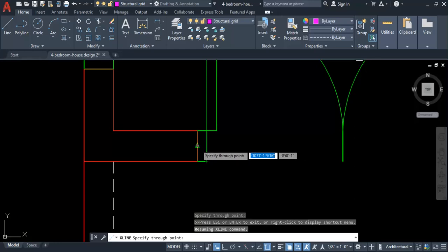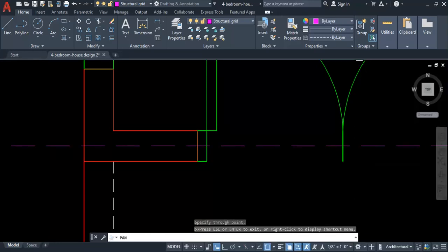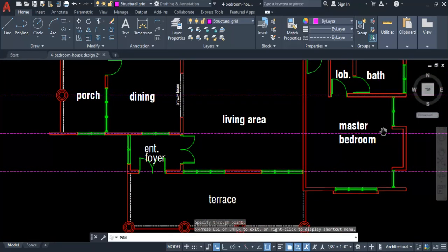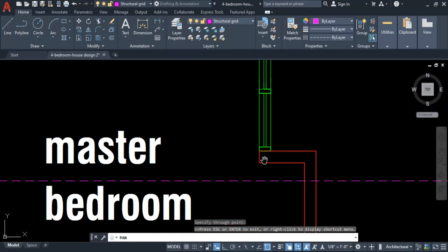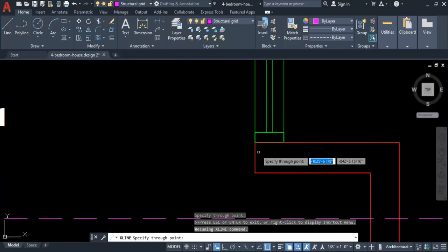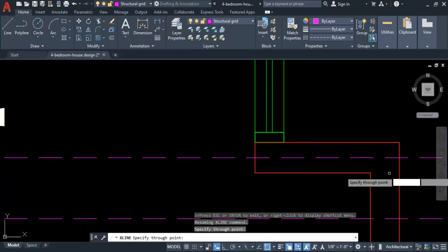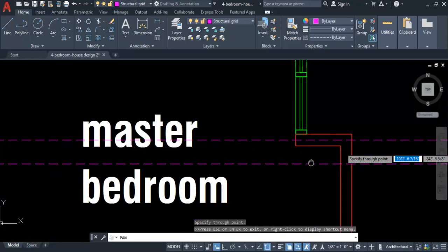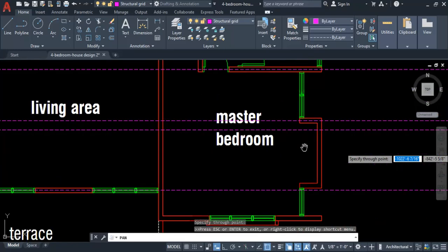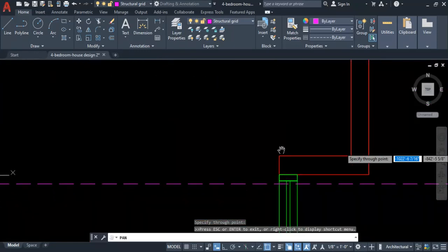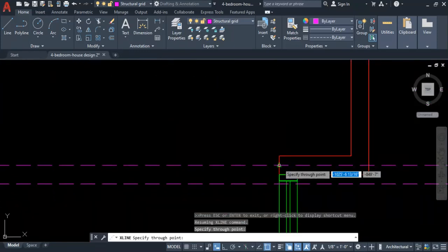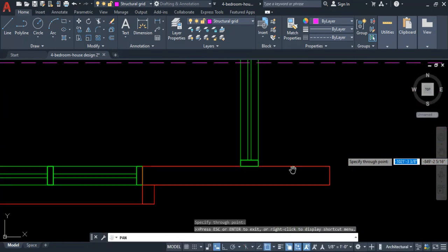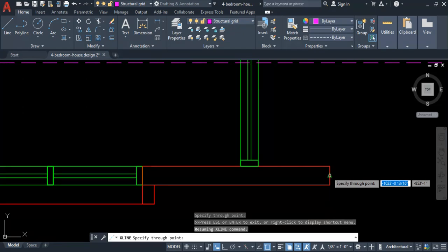Okay, so we also have one. You place this one here. Okay, then let's see. Okay, although we might not need this, but let's just place this. Then after placing the column, whatever grid is not needed, we can just delete the grid. But for now, for any horizontal wall, you place the horizontal structural grid. So this one also, you place the grid here.